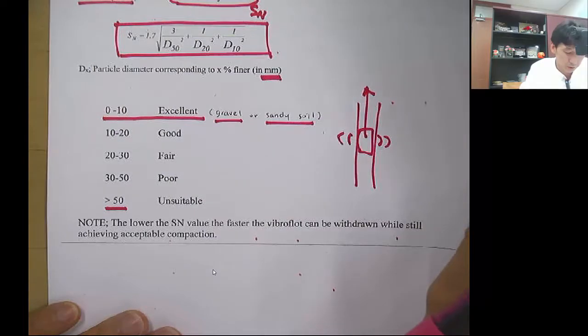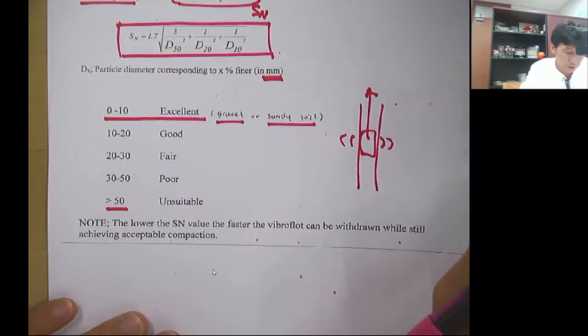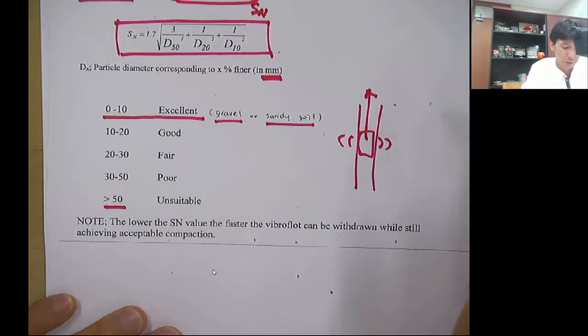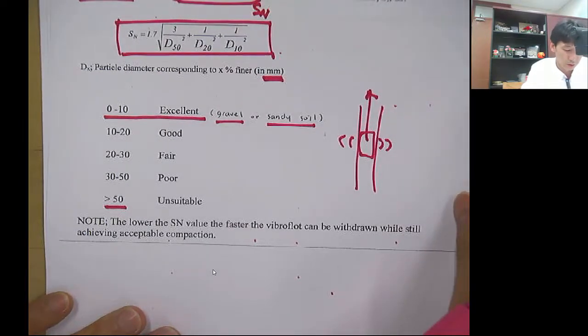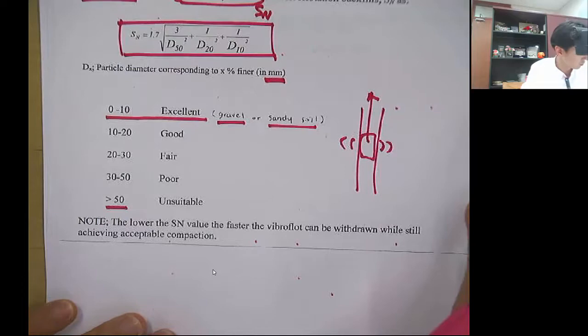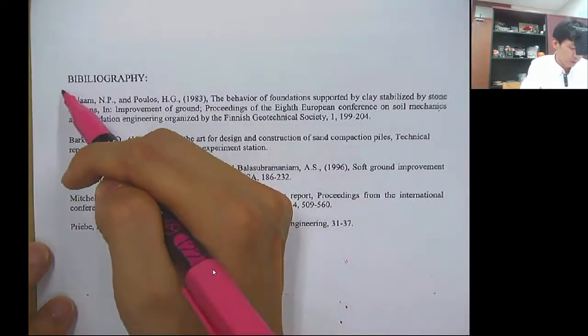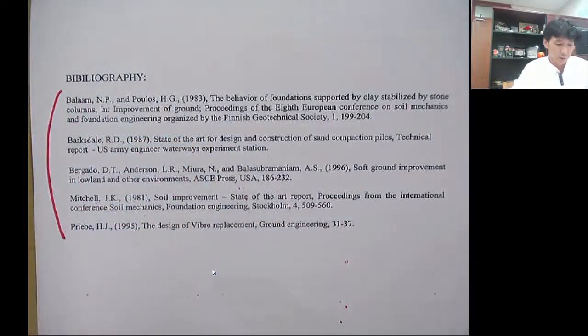So you have to wait until it densifies sufficiently, and then you move up to the next lift. Here are the important references for the vibro compaction.